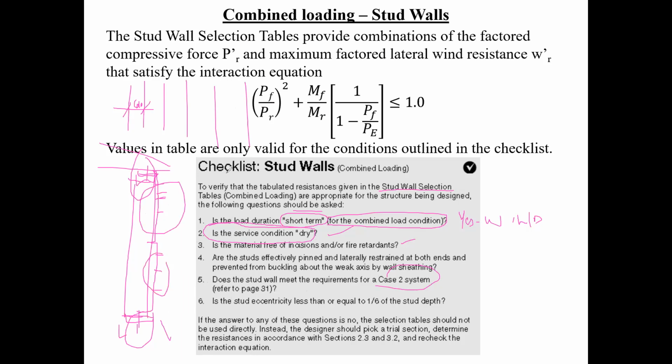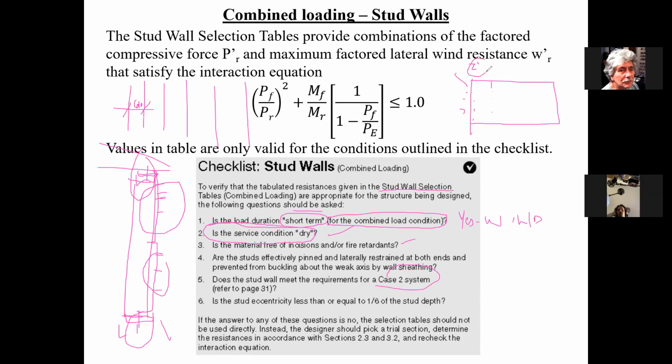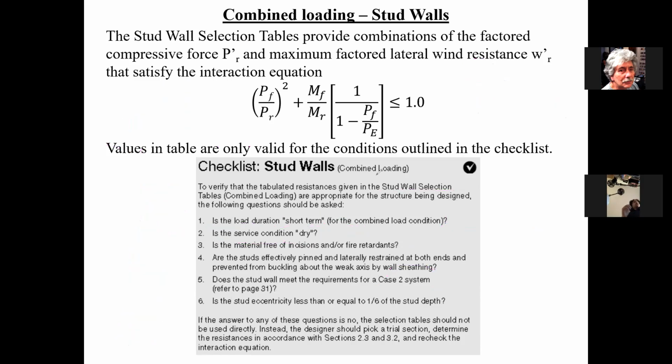Okay. And normally, if you're doing a lot of wood structures, you'll have a typical detail sheet, and on that detail sheet you'll basically show a plywood sheet, and you'll show along the edges you want the nails to be at every 150 millimeters, and in the intermediate, and you'll have a typical detail telling the carpenter, and you're going to specify a minimum of 2-inch nails. You understand? So this is what they normally do. So the carpenter will probably use 3.5 inches and so on. So, and therefore the answer would be yes.